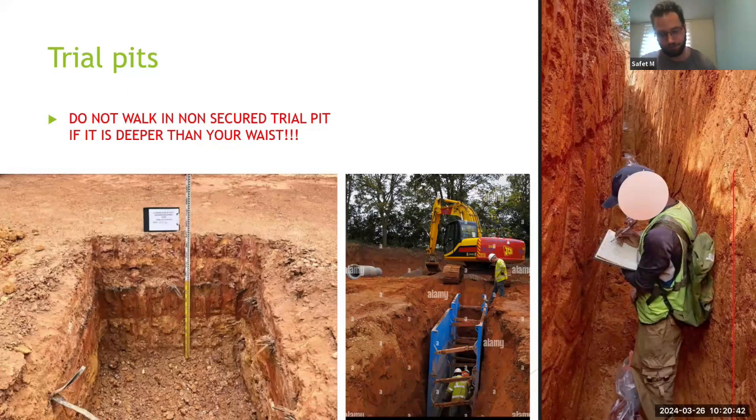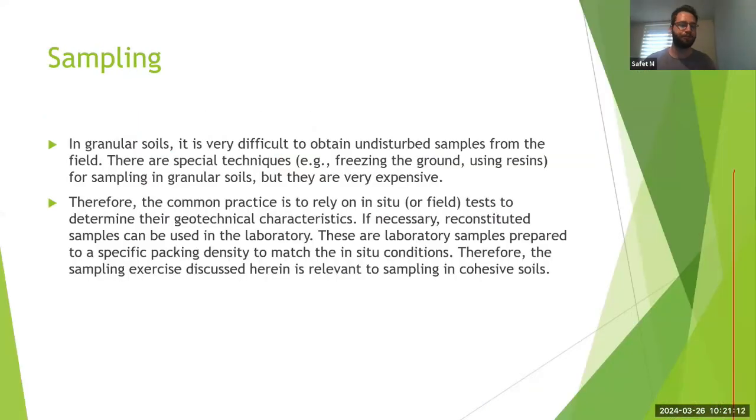Generally speaking, you're unlikely to be asked to do such a thing, because most of the things you can just see from the surface. Just go and take photos. You're going to go there with your measure tape, take pictures, and if you need to take samples, go there after it's protected. Usually, we would say that if it's more than 50% of your height, don't go into the trench.